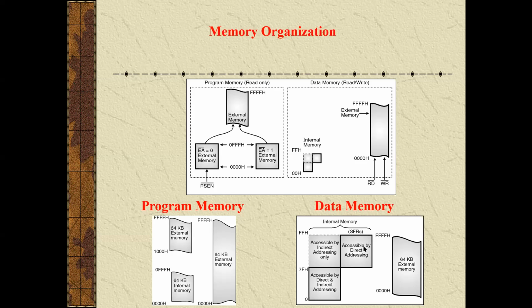Now let's see about data memory. The 8051 microcontroller can address up to 64 KB of external data memory, as shown in the figure. Here the command MOVX is used to access the external memory. How can we access the external memory? By giving the command MOVX.